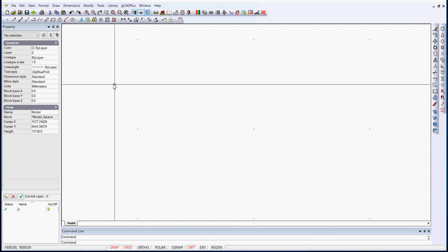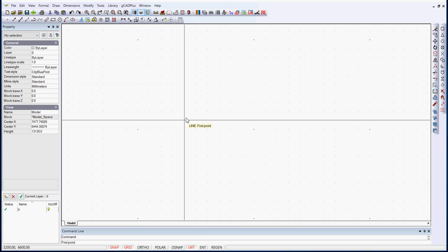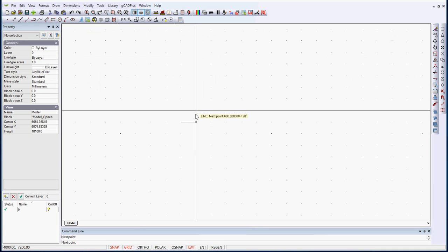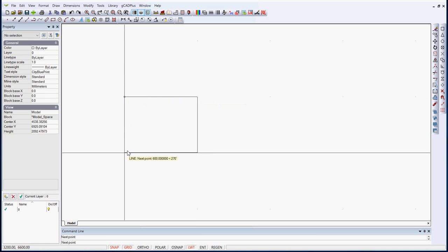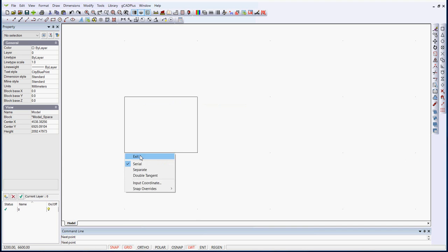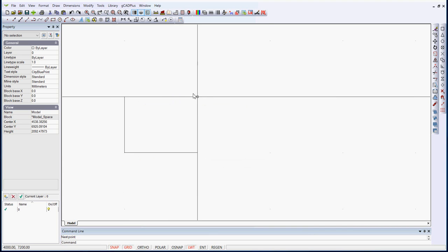Let's just return to our background colour of white, where the grid doesn't show up quite as well, but it is there. So if I want to draw a paving brick, I simply pick up the line command, and no matter where I click on the screen, it anchors at a grid point. And you can see as I move across, I'm moving in steps of 800 when I go horizontally, and when I go, let me zoom in, and when I go vertically, I move in steps of 600, come back over here and back to that point there and exit from there. So we've drawn our paving brick relatively easily.